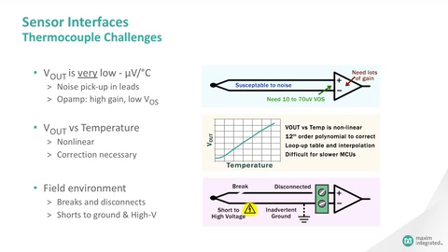The relationship between temperature and output voltage for a thermocouple is fairly nonlinear. In the curve to the right, it's fairly obvious that the portion of the curve on the lower left is quite nonlinear. If you look carefully, you can also see nonlinearities in the rest of the curve. As a result, any system which uses a thermocouple as its measuring device will require some mechanism to compensate for these nonlinearities. This compensation is resolved with a 12th order polynomial, a CPU-intensive calculation that is difficult for slower processors. This is often simplified by the use of a lookup table.